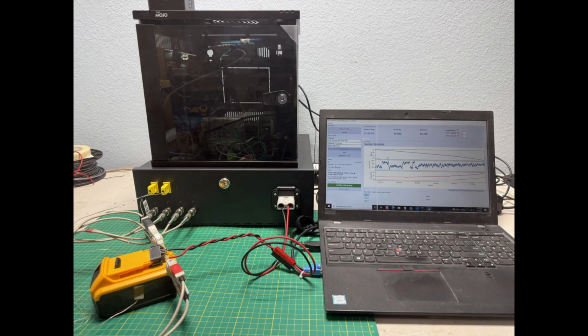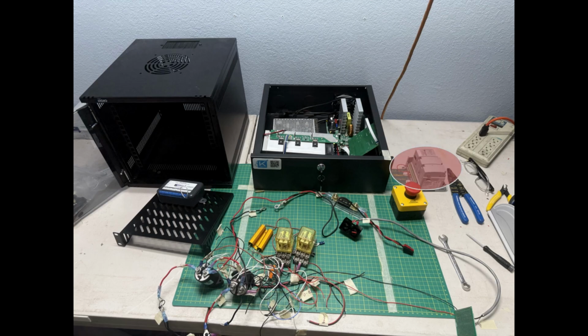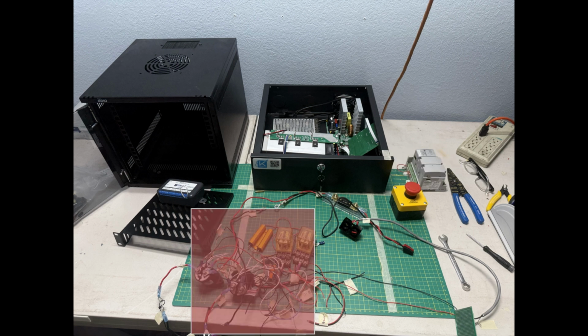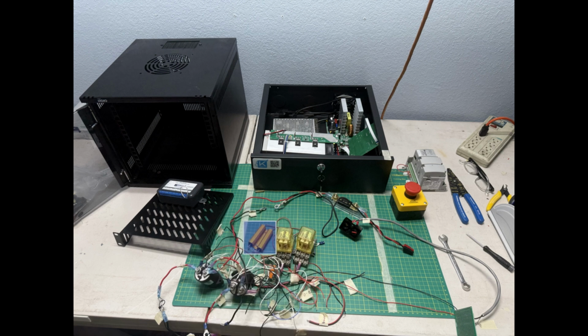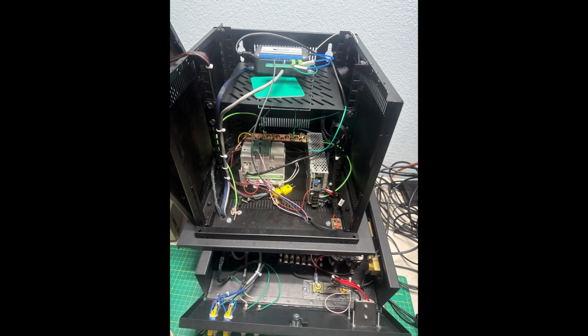We've been working on building battery analysis equipment and software development for a little while now, and we now have a solid working system. It consists of a PLC that opens and closes contactors, isolating both positive paths of the load and the supply systems, as well as a resistor block to bleed battery voltage to prevent any arcing in higher voltage applications while attaching the battery or switching the contactors. This particular system is really only rated for about 30 volts or so. It's just a prototype demo unit.